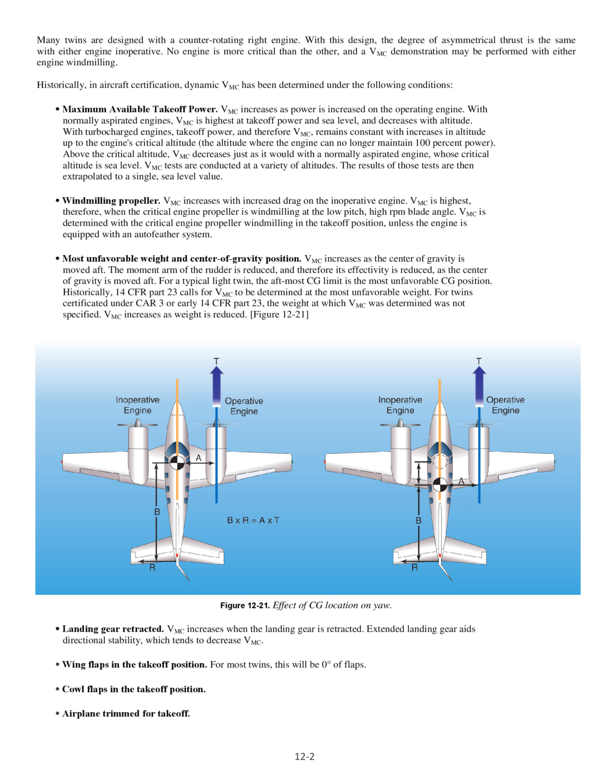VMC is determined with the critical engine propeller windmilling in the takeoff position, unless the engine is equipped with an autofeather system. Most unfavorable weight and center of gravity position: VMC increases as the center of gravity is moved aft.